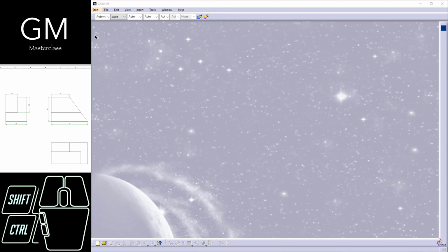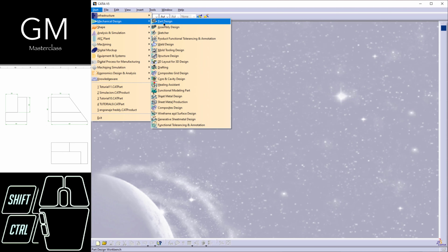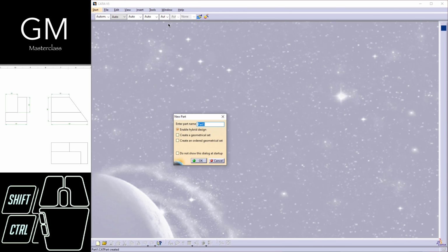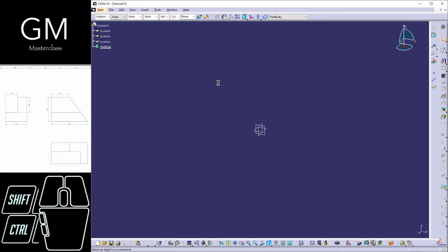I'm gonna start by clicking on Start, Mechanical Design, Part Design. This is going to be a part. So the part name will be Tutorial 12, because this is the 12th tutorial within the channel. I'm gonna select that this is going to be my lateral view or my front view. I don't really care about that.